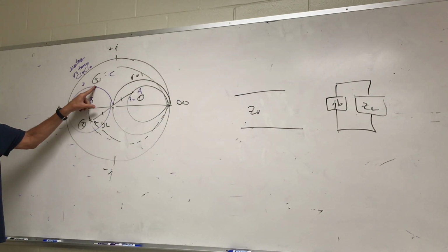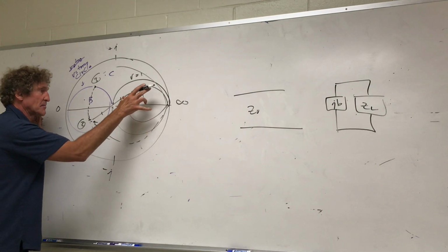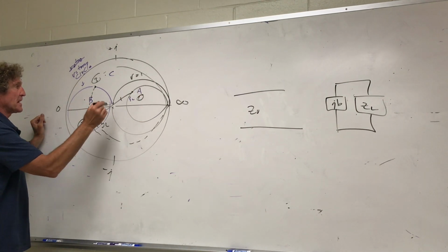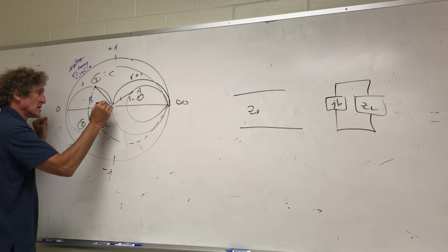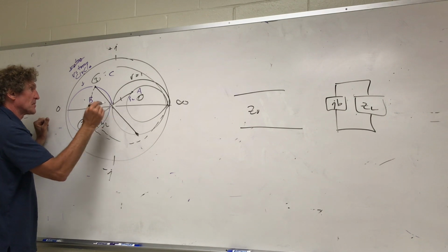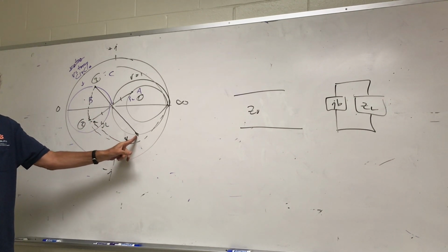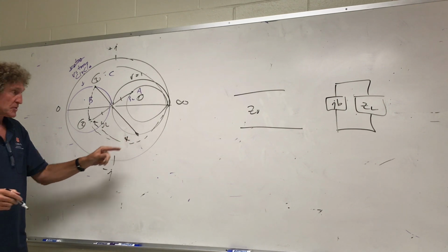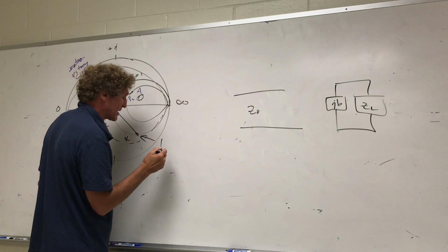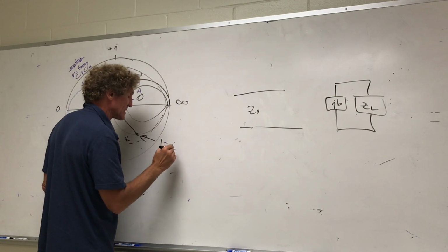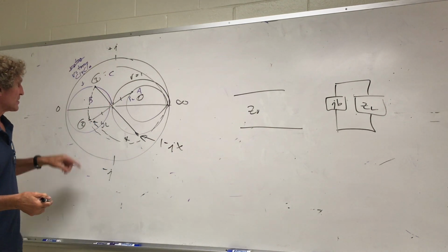Now once I'm there, the beauty is, and that's the reason the second circle's right there. It's absolutely the same radius, everything, just folding this. Now when I go back from the admittance domain to the impedance domain, so this is part 3, and go here, this will land on the one circle, 1 plus or minus j something. So this must be 1, and it can be plus or minus. In this case, it's going to be 1 minus jx, and I don't know what x is because we've got to go from here to here.